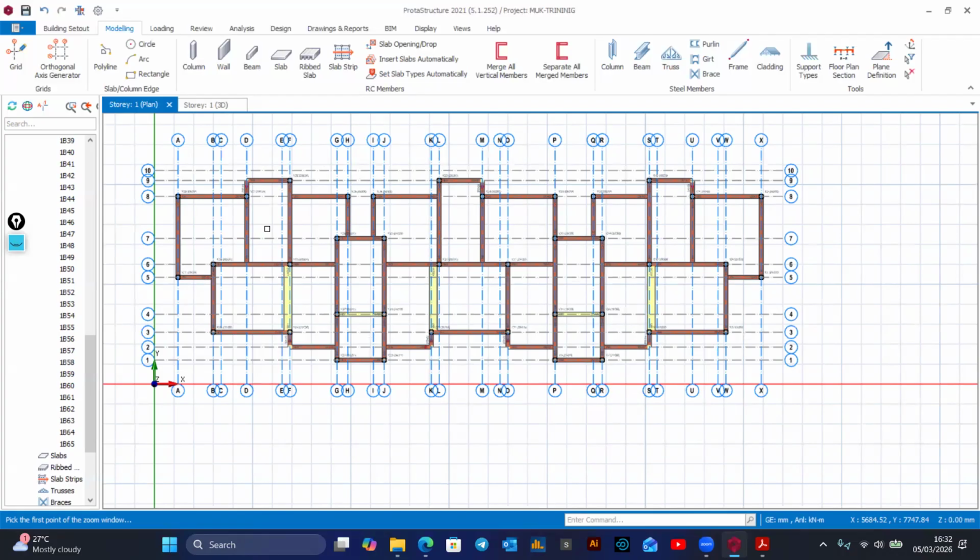When there is no basement, it is very fine. What we are looking after in design is deflection and bending. So you are already on ground floor level. You are putting hardcore, you don't expect bending at that level. You get it? So we don't design that level completely, we just put oversight concrete.